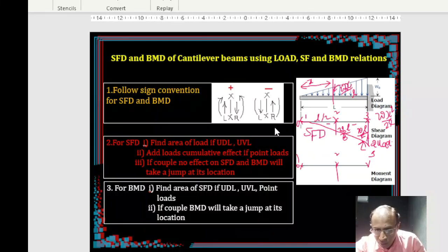By the way, the bending moment is also negative, because we are moving from left of the section, clockwise only is positive, and our moment is going to be anti-clockwise because the loading is coming this way. Okay, so this is W naught.